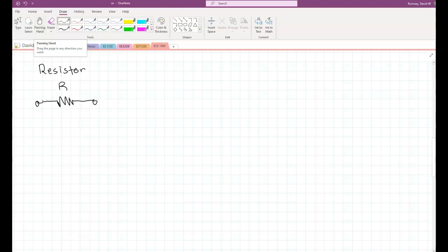And so when we have a resistor here, what we will do is apply a voltage across the resistor. So I'll just label that as plus minus V. And the positive and negative for voltage, of course, matters. And we want to know that because then I also want to know what's the direction of the current. Well, the current is going to flow from the positive side to the negative side. So we'll call this current, and we give current the label of I.